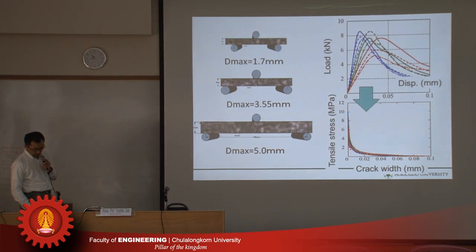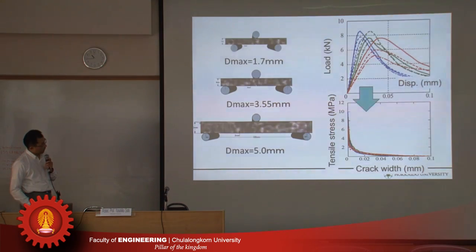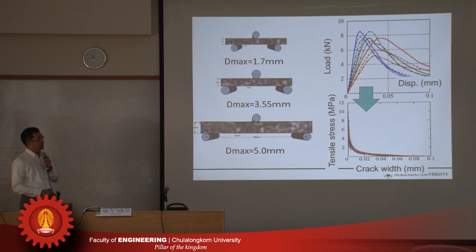And of course, before this kind of observation, we checked the influence of the size of the specimen and the influence of the size of the fine aggregate. Of course, the load displacement curves differ for different sizes, but the local response, I mean the softening curve, is not affected so much within the range of the size of the fine aggregates.